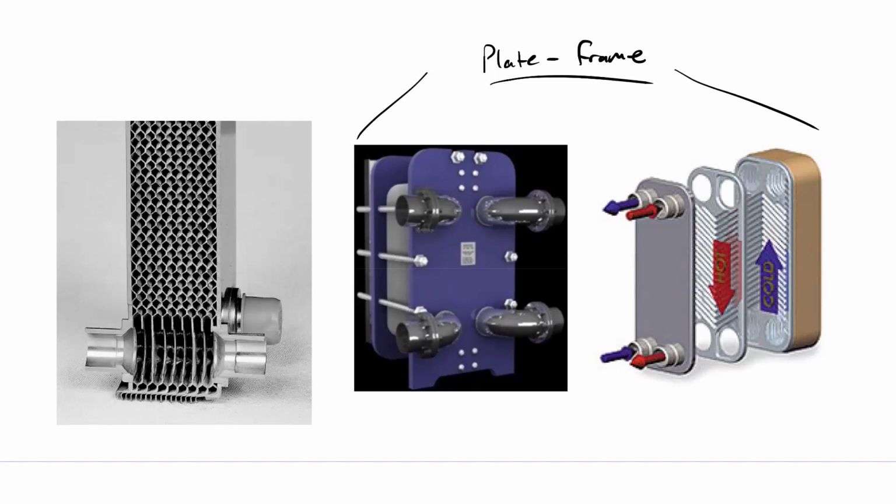But if you wanted to add area to your heat exchanger, say you're changing your application to need more power, something like that, you can just take these bolts right here, unscrew them, pull them out, add plates, and now you have a bigger heat exchanger. As opposed to some of the other geometries that are really fixed. We'll see. This is a really common one that shows up a lot for different applications.